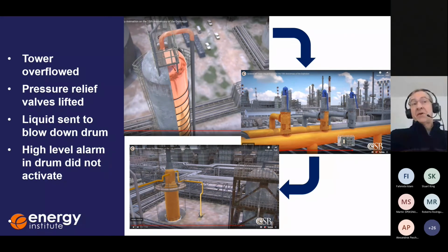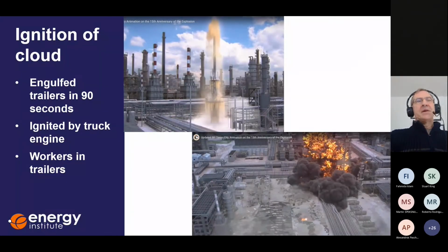Again, the high level alarm in the drum did not activate. So again, the operator would have no indication of the level, or indeed of the liquid being in the blowdown drum. The operator was unaware of what was happening. The blowdown drum continued to be filled, and ultimately, like a fountain, the hot flammable liquid